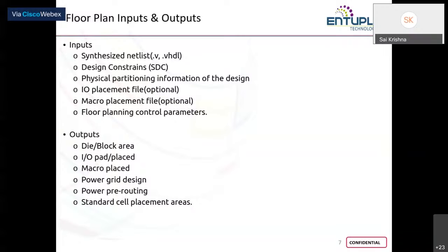There will surely be a difference when you look only at a block and how the pins could be placed, compared to looking at a complete chip and understanding what the pins of a sub-block are that are communicating with another block, right? So when you look at the chip level, you understand that certain pins need to be placed in a certain manner in order to be close to its communicating second sub-block, right?